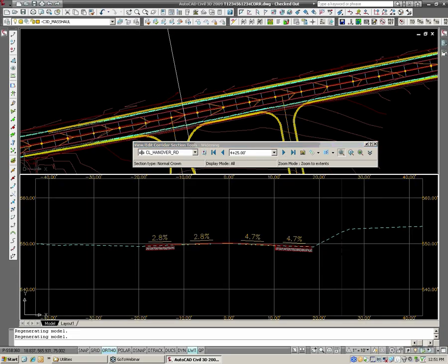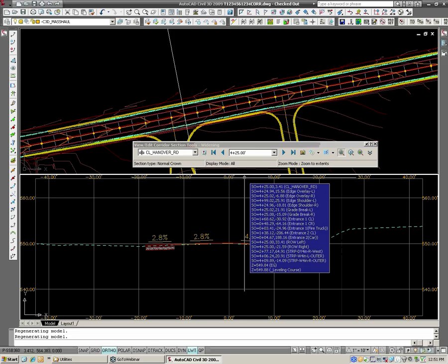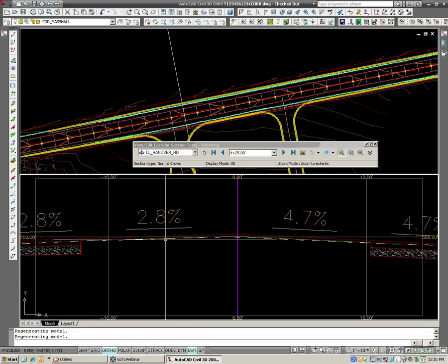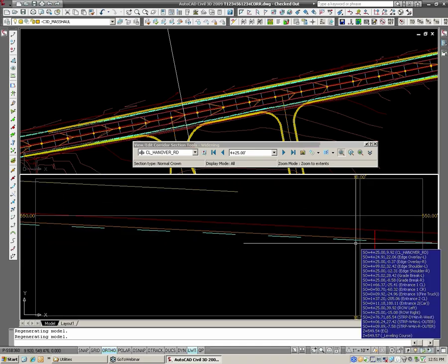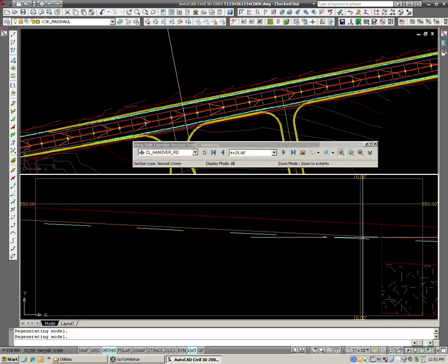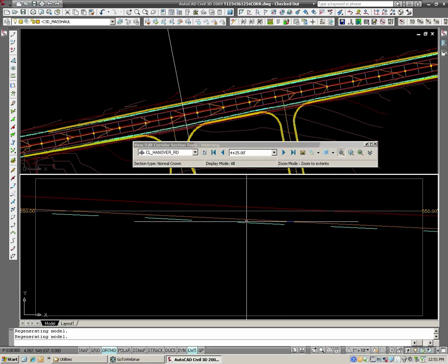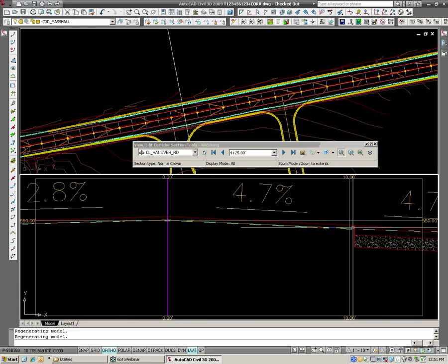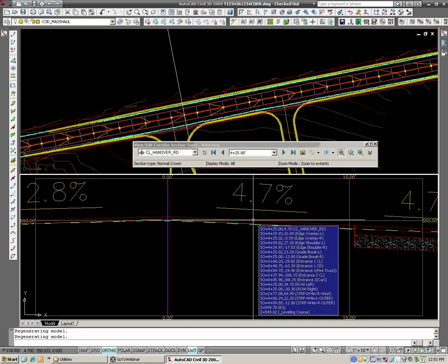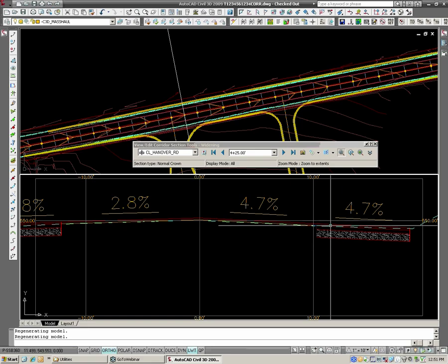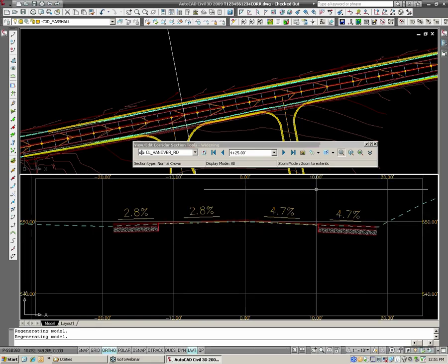Of course, if I go and make an adjustment in any of those 3 profiles, that adjustment will either raise or lower the center, this edge, or this edge. You can actually see, hopefully on the screen, the brown line here. That brown line is the top of my leveling course surface. All right. So if I make that adjustment, it would automatically rebuild that corridor, which would automatically rebuild that top of leveling course surface, which would automatically rebuild my new widening corridor here.